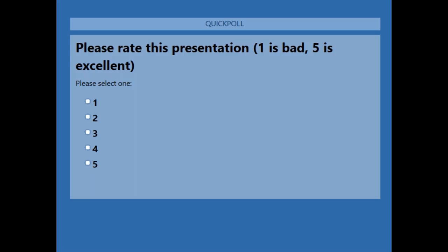Okay, fantastic. Josh, you agree with that? I would assume. Yeah, just make sure that that maintenance switch is on the feeder breaker feeding that MCC and not on the main. If it's on the main, you want to be careful about using that reduced rating if you're working in the main section, because then that value wouldn't apply. So just keep in mind what piece of equipment that switch is on when you're applying that label value.